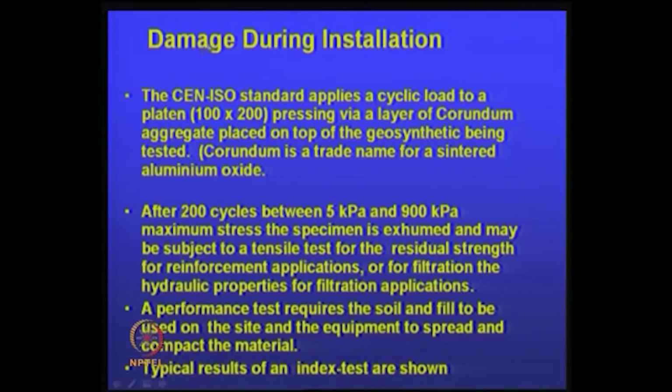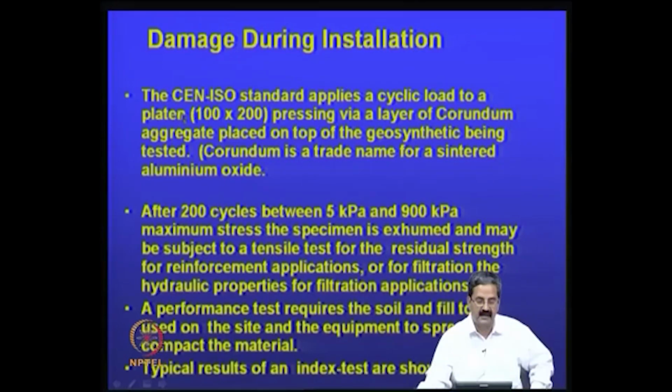There is another test, if you want to understand what damage can occur during installation. This is a European standard in which cyclic loads are applied, 200 cycles between 5 and 900 kPa, and the maximum stress is assumed. After the maximum stress, the specimen is removed, and again you test it for a tensile test or a filtration test.